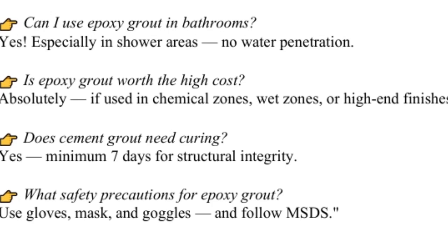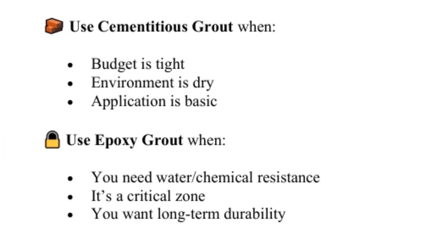Does cement grout need curing? Yes, minimum 7 days for the structural integrity, or as per IS 456, whatever minimum period of curing is mentioned, you need to follow that. Now, what safety precautions for epoxy grout? Use gloves, mask, and goggles, and follow the MSDS. What is MSDS? Material Safety Data Sheet. The Material Safety Data Sheet clearly mentions how you can handle the epoxy resin, hardener or the filler material, because it's harmful. If it goes inside your body, it can damage your body. So you need to first find out what is written in the MSDS.